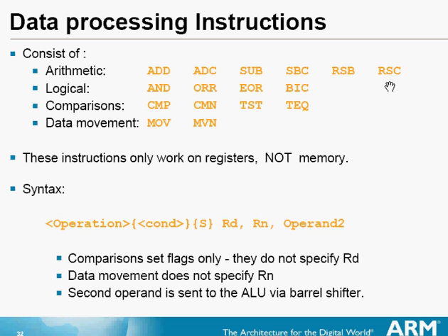CMP is like subtract. CMN is like add. Subtracting a negative number is the same as adding. TST is like AND, simply. TEQ is like EOR. EOR of identical numbers gives result 0. So these instructions only work on registers, not on memory.